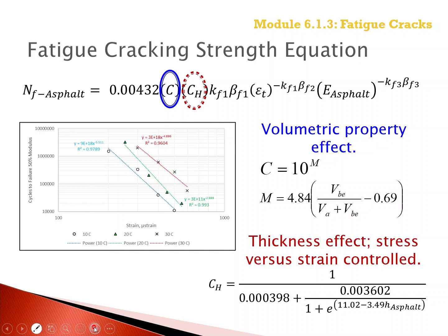As mentioned in Module 445, a standard practice was prepared for AASHTO to provide guidelines for interpreting the outcome from the fatigue strength test to derive the fatigue strength coefficients of the bottom-up fatigue cracking transfer function that are entered in the PMED design software. The AASHTO standard practice is available from AASHTOware.